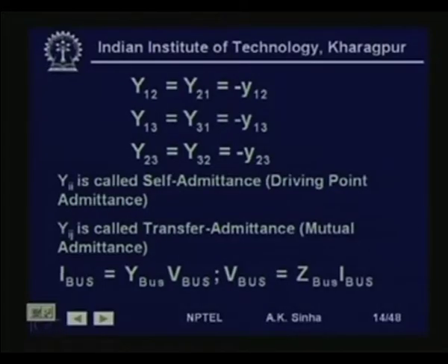In a very large network, say a 1000 bus network, on an average each bus will be connected to just 2 or 3 buses. So, in a particular row you will have only 3-4 elements, the diagonal element and 2 or 3 elements of the other buses connected to it; the rest of the elements are going to be 0. So, Y bus is a very sparse matrix.